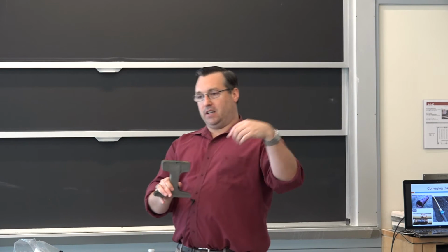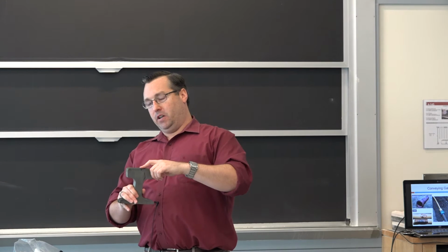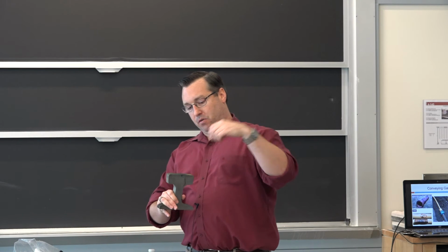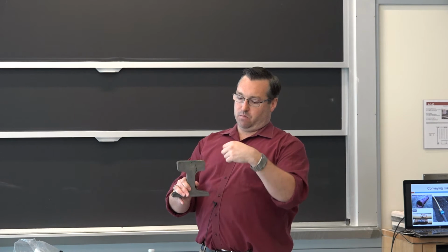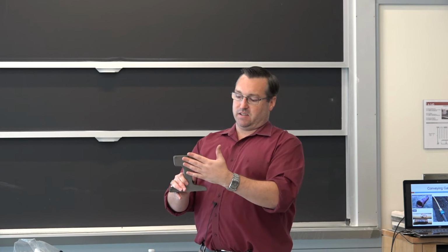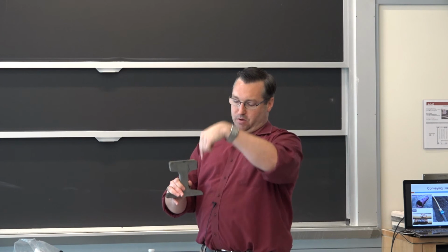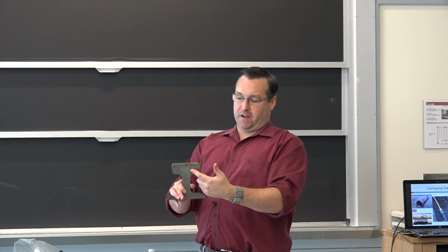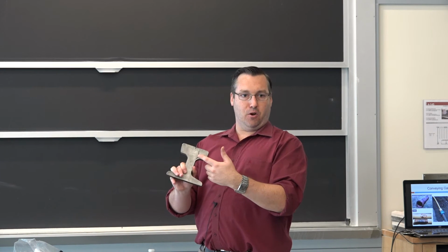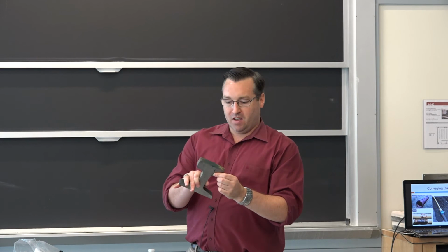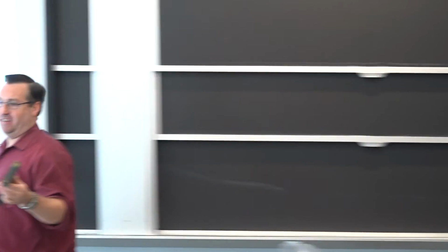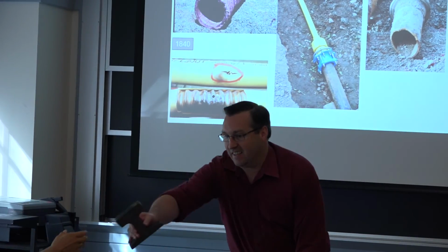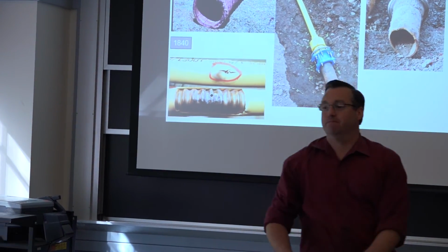In the ultrasonic inspection, you use a couplant material, put it on, and then you check the consistency of this with sound waves, so it goes through, and you would have gotten an indication that showed this was here. But this got put into service, so ultimately they had to replace that whole section.